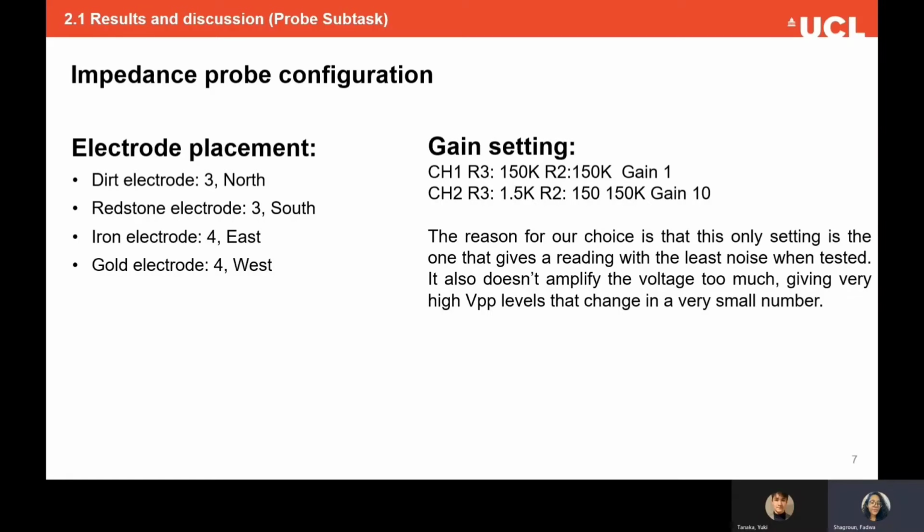We chose to place our gold and iron probes opposite to each other at a height of 4 blocks. The reason is because we assumed the signal would run across the largest amount of solution possible, such that it would be representative of the total volume being tested. The input was placed perpendicular at a height of 3 blocks. We placed it so that it would be out of the way. Lastly, the ground went perpendicular and below to the gold and iron probes at a height of 3 blocks so that it doesn't interfere with the signal but could pick up excess charges as it's meant to do.